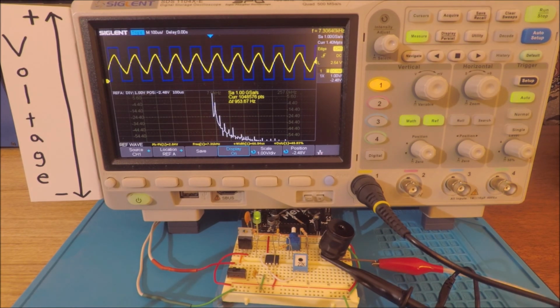Right off the bat in the time domain, we can see that we've almost perfectly filtered out the fundamental sine wave. That would represent the fundamental in the mathematical Fourier series summation. So this increased filtering, being a second order filter, has further suppressed the harmonics, but has retained the fundamental frequency right here. And that's what we're seeing in the time domain. Compared with the first order filter, the peak-to-peak value of the residual signal is much larger because of that resonant peak of the filter being aligned with the fundamental frequency.